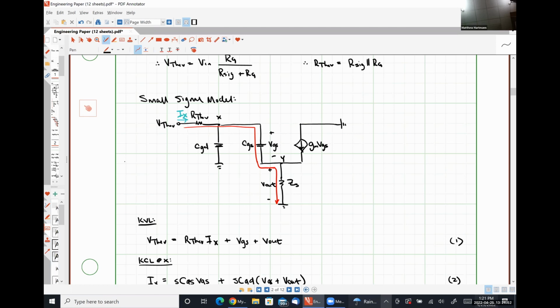Anyway, applying the Miller method here, which I'm going to ask you to do in your homework, would allow you to effectively analyze the circuit at node X to find the resistance connected and the capacitance connected, analyze the circuit at node Y to find the resistance connected and the capacitance connected, and then get your poles from that and be done with it.